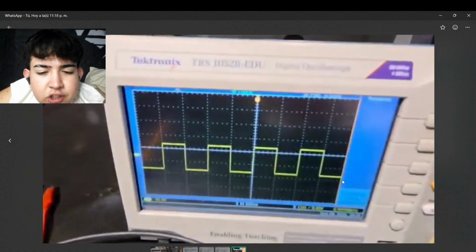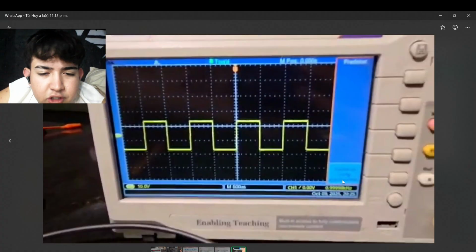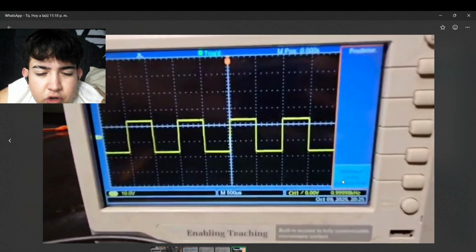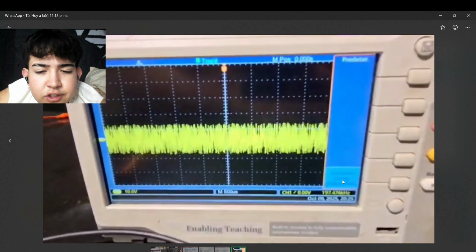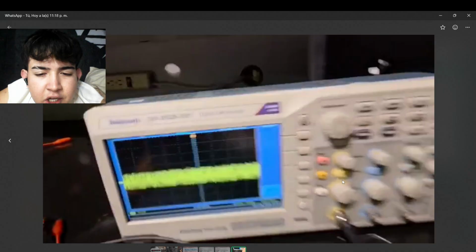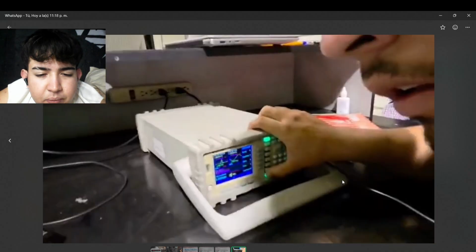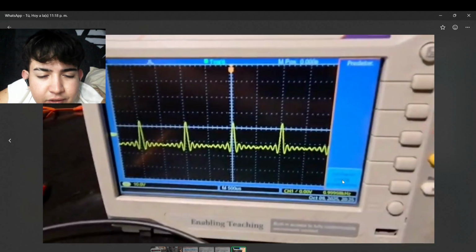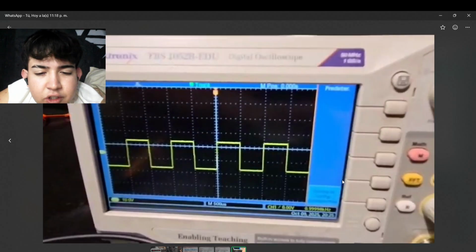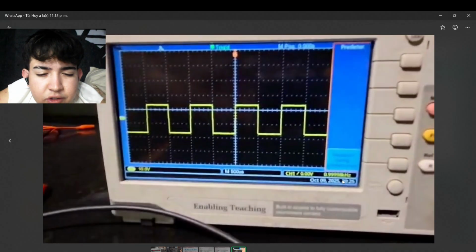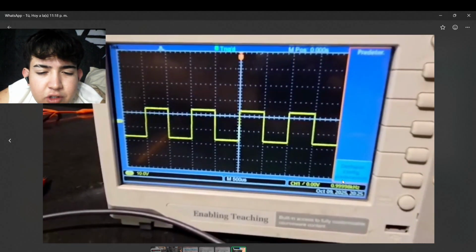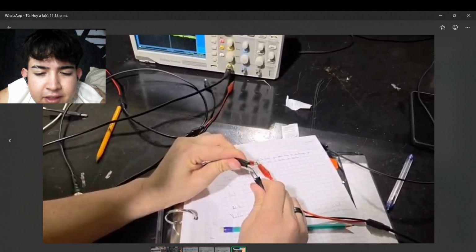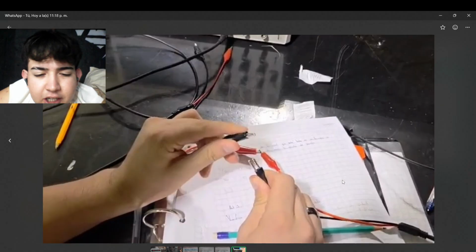After connection, the signal was observed on the screen, recording the initial peak-to-peak voltage (Vpp) and frequency in hertz values. The oscilloscope was then calibrated using the default or offset function. After calibration, the Vpp and frequency values were verified again with no significant change observed, indicating a correct initial calibration of the equipment.